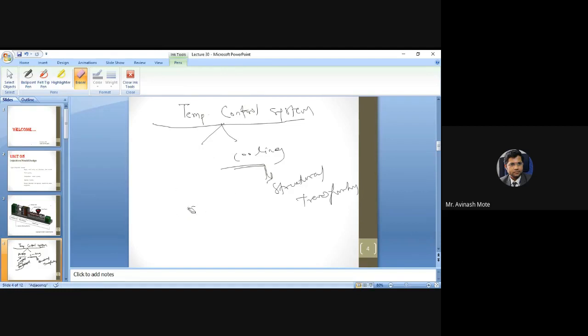The most important role in the temperature control system is that of the cooling system, because the type, quality and uniformity of the product are all managed by the cooling rate or the cooling parameters, because structural transformation occurs during cooling.